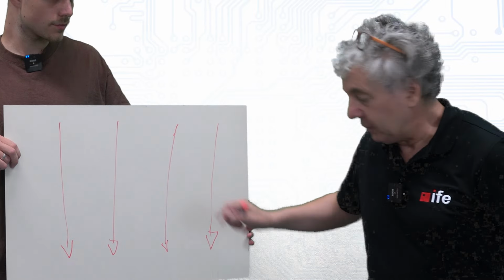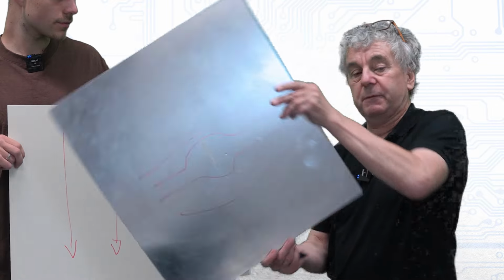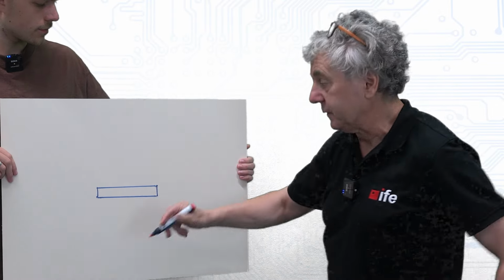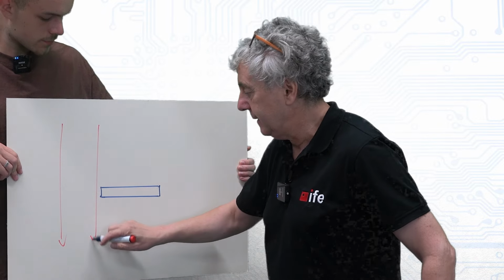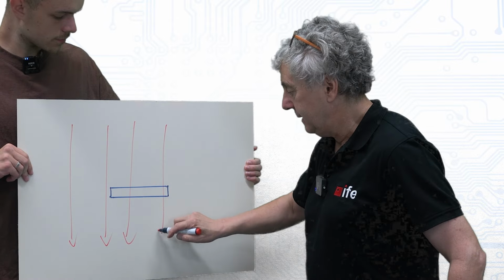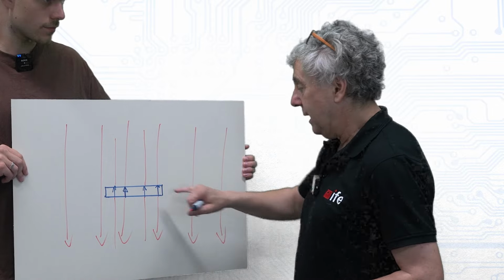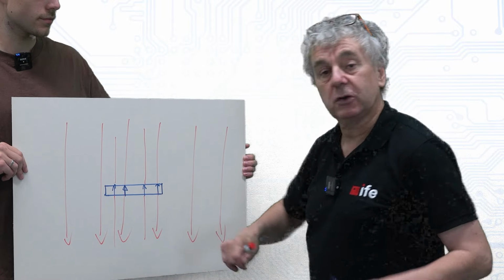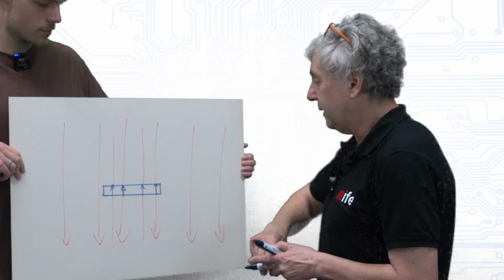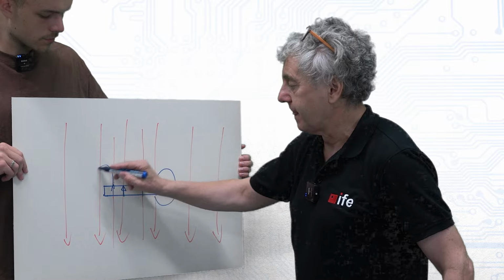Now imagine we don't have a solid metal piece, but we have a metal piece with a slot. So the current without the slot would flow like here, here, here. This is the current without the slot. But there's a slot, the current cannot flow there. So there must be inverted current here in the slot. This is an inverted current, and the inverted current makes sure that this current gets cancelled, because there's a slot that cannot flow. But the inverted current not only flows in the slot, it has to have closed current loops. So the inverted current would flow also like this.